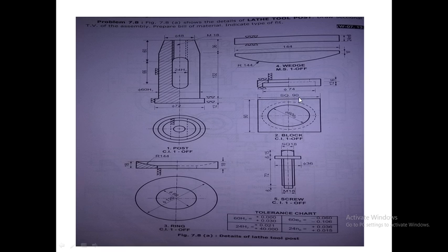It is written here as SQ90, which means the square is of side 90 mm. Now this square block has two holes inside it. The first hole, the upper hole from here to here, is of diameter 60 mm, and it is visible from the top, so it is drawn as a dark circle of diameter 60 mm. Whereas the bottom hole, which is of diameter 74 mm, will not be visible from the top view, so it is shown as a dotted circle.